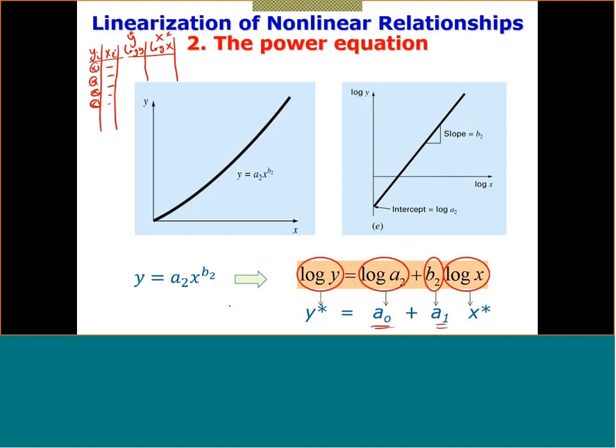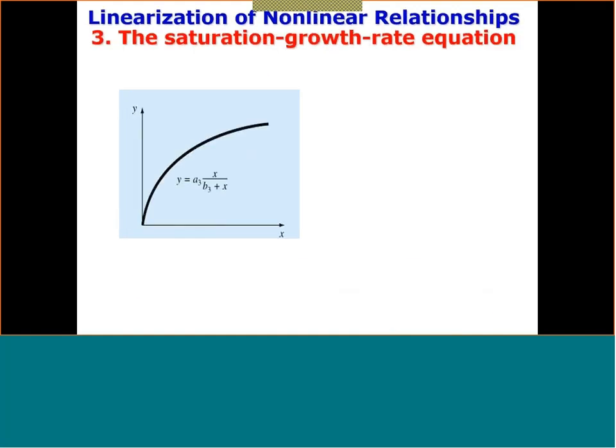Let's see another equation. This is called the saturation curve. We see that in many practical aspects in electrical engineering, like for example, for a real inductor, the flux-current curve follows this shape. So in circuits, we assume that the inductor works only in the linear region, but after that it becomes non-linear, and you might cover that in some advanced courses in power engineering, or in electronics maybe, or maybe in electromagnetics.